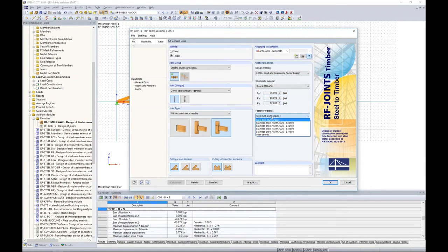The fastener material, again, some ASTM standards or user-defined. We will stick with J429 with a yield KSI of 48. The checkbox calculate with members in contact. If we were to turn this on, this essentially just tells us that we're considering 2 members are in contact. And if we have extremely high pressures from one member down onto the other member, the program will actually flag us and tell us, well, this is something that you may want to look into further.